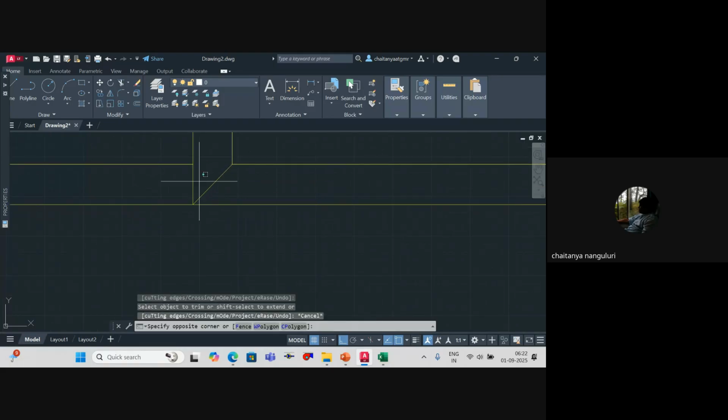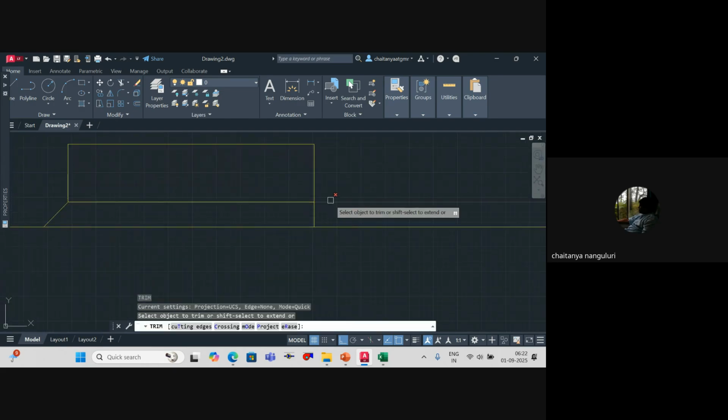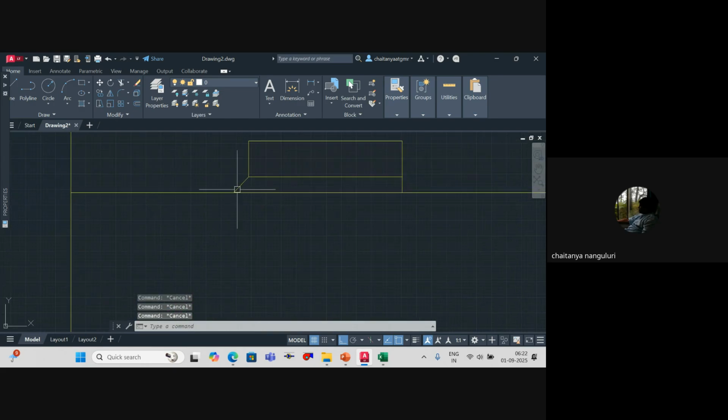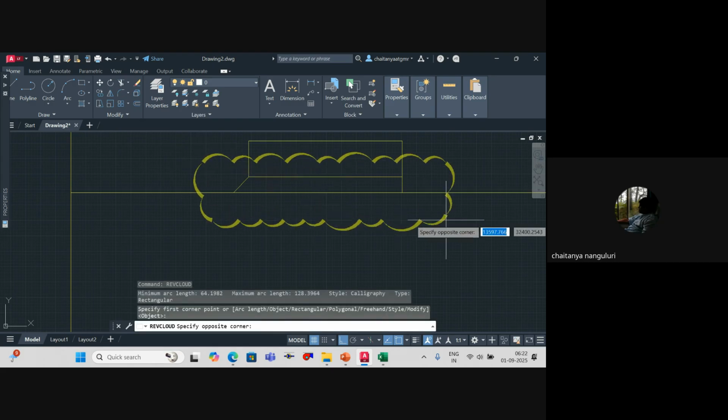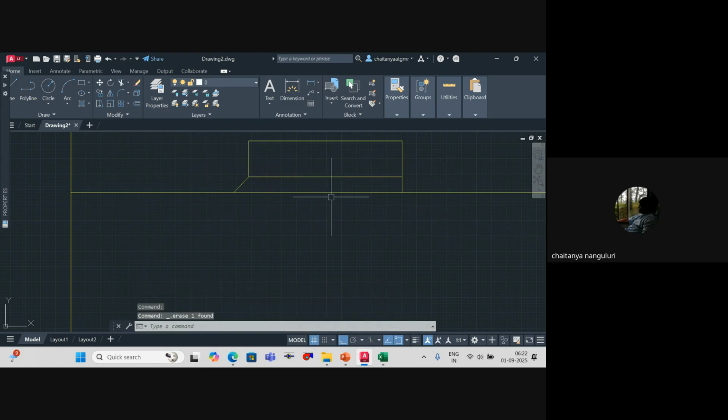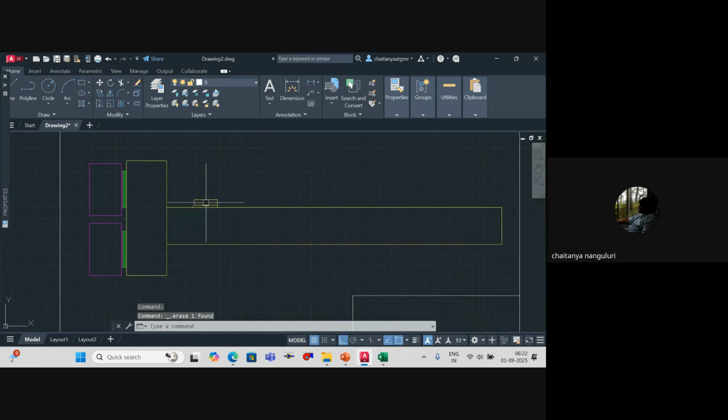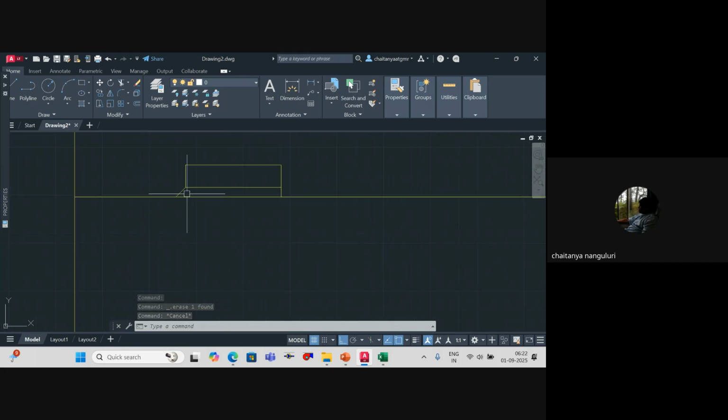So this piece, we call it a collar. Whenever you observe a collar, there will be one more component additional to this size, some additional protection, which we call a shoe piece. Understood? What do you call it? Shoe piece. The reason you have to install a shoe is simple. Can you guess the reason? If the airflow direction is like this, it should always be parallel to the airflow direction. Can you guess why I want this particular shoe piece?